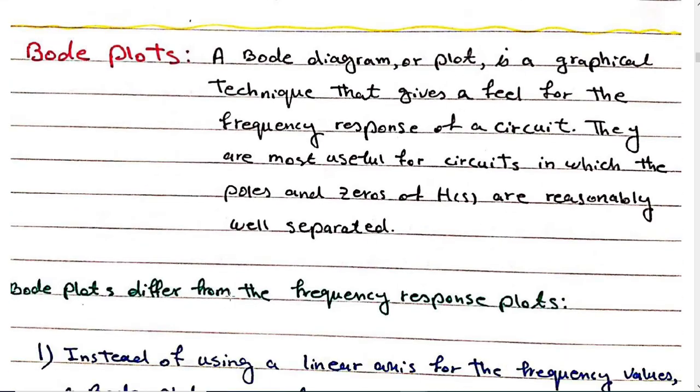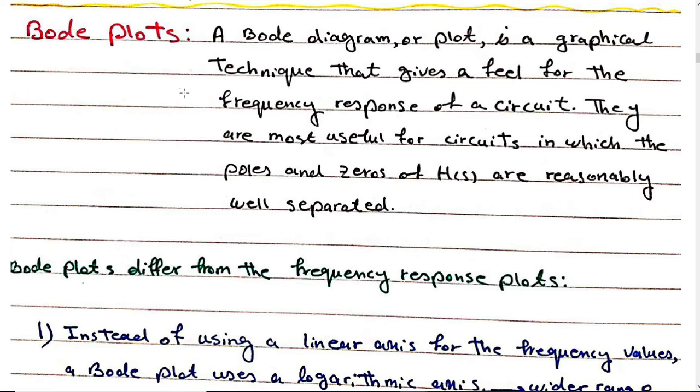Bode plots. Did you study this kind of plot before? A Bode diagram or plot is a graphical technique that gives a feel for the frequency response. From the plot we can understand the gain of the filter, what kind of filter we have, and the cutoff frequency.